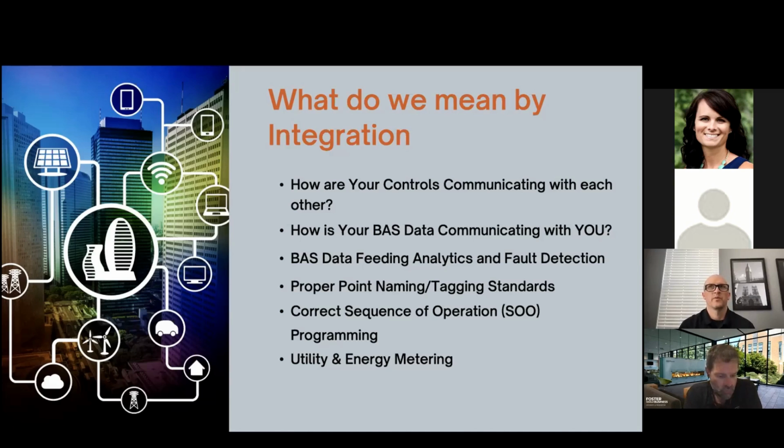Yeah, and it sounds so simple to say, hey, are your points named correctly? And people might shrug that off, but it really is amazing how critical it is, whether it be point naming or just getting your hierarchies correct in terms of your parent-child relationships. It's so critical, and too often it gets passed over. That type of integration, you think you're writing a sequence of operation, you walk away and forget it. But if your VAVs downstream are not tagged to the correct air handler, you could have the greatest static pressure reset sequence of operation ever written. But again, if those hierarchies and those point naming structures and naming conventions aren't correct, it's never going to work.